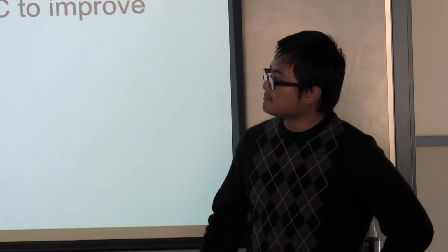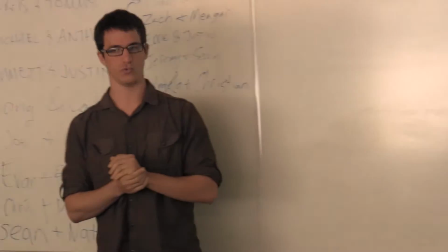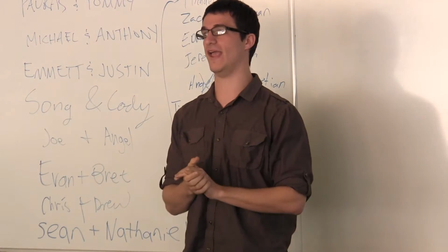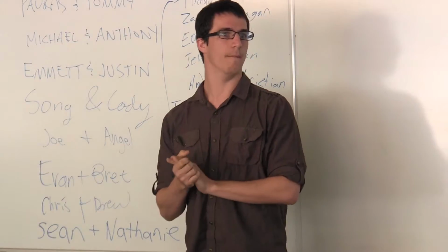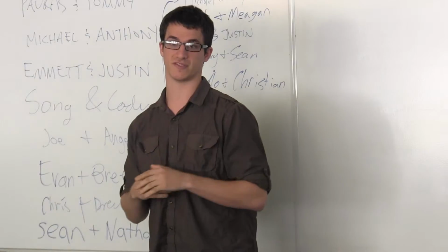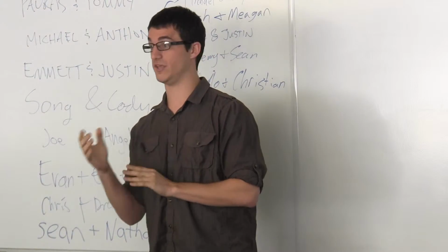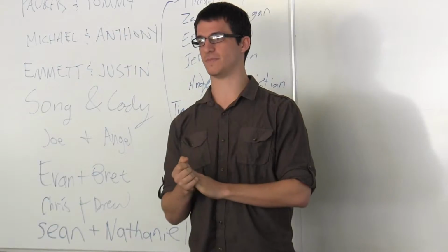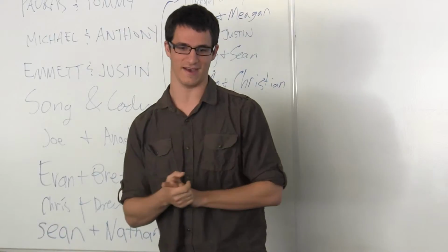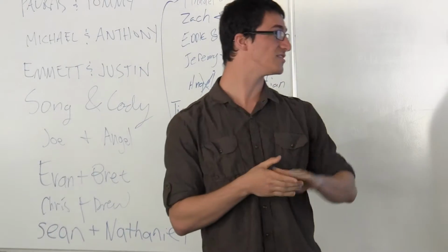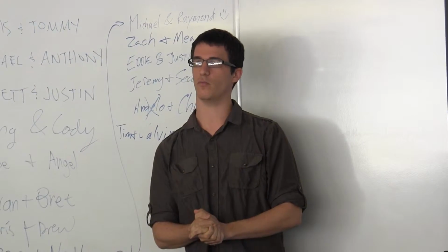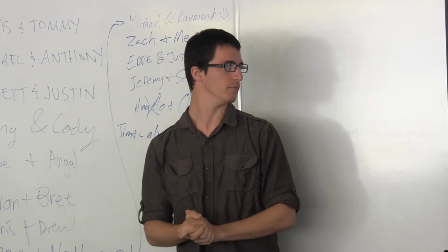And we would also want to implement a digital noise filter because we have analog filters on our board, but getting these filters to be super precise, so your audio sounds really good, can be pretty expensive. It takes a lot to make analog filters precise, so there's a lot you can do digitally to filter out noise, but we weren't able to figure out how to do all that completely.